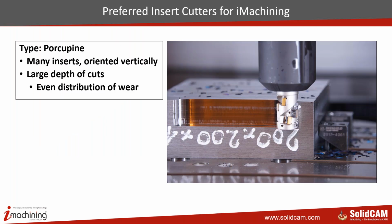So what is the preferred insert tool for use with iMachining? The porcupine style. These cutters have many inserts aligned vertically. The vertically aligned inserts allow for large depths of cut. This is one of the major benefits of iMachining. It is the ability to take large step downs. Having inserts aligned vertically allows for even wear distribution due to the many edges being used at once.